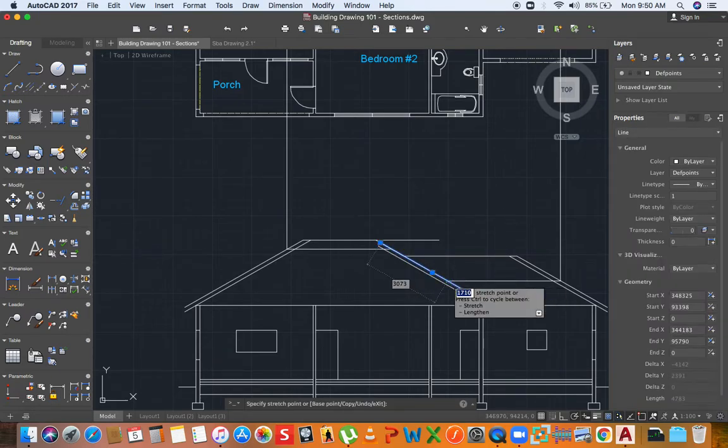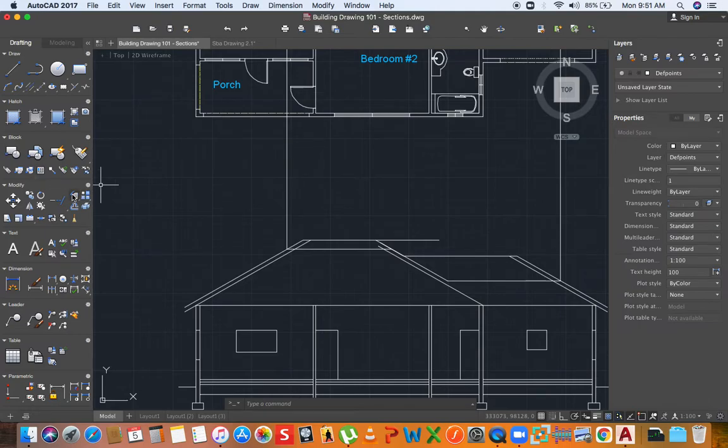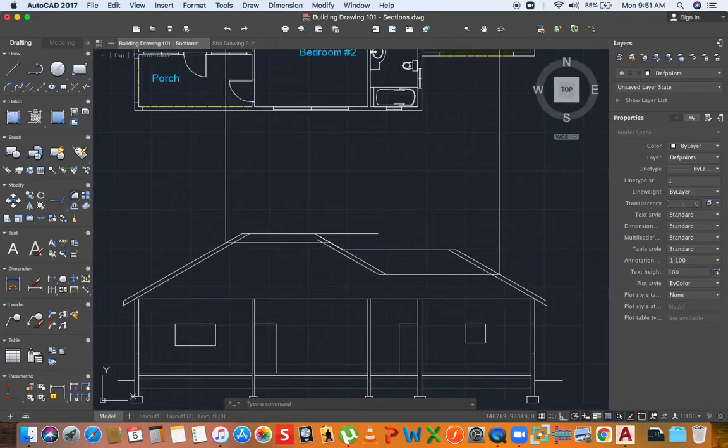So you bring this up to here, and you fillet these. Alright, for the edges of the roof, now you have to close them up like this. And then another thing to bear in mind, after where the roof is cut, you will see it like normal, like it's an elevation.